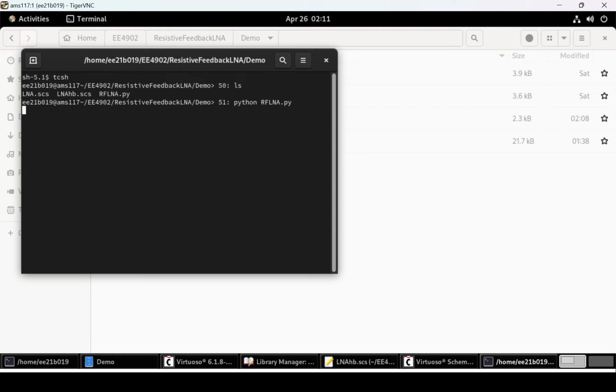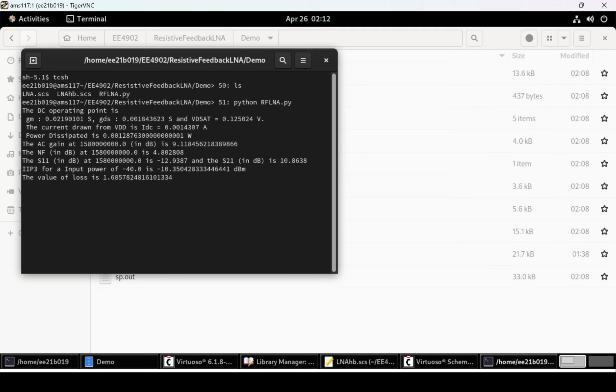Unlike the previous case where the best 3 netlists were picked based on the loss and the sensitivity and PVT variations were performed, in this case I will pick only the best 2 netlists and run the PVT variations and temperature analysis.